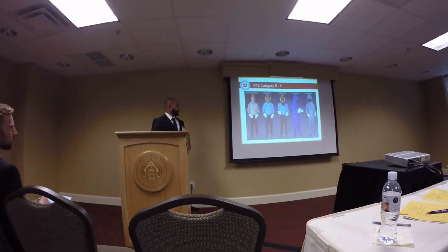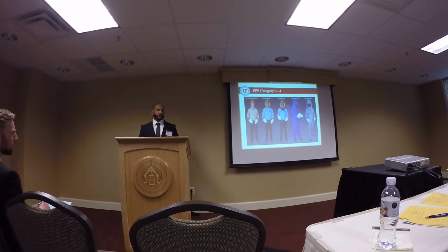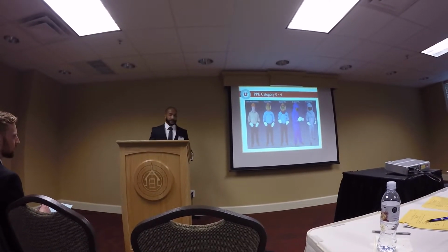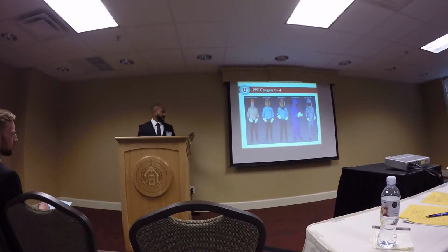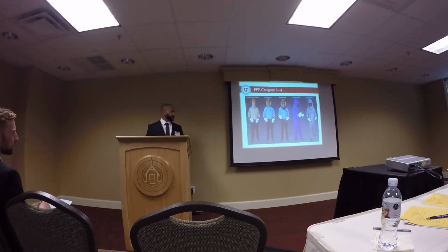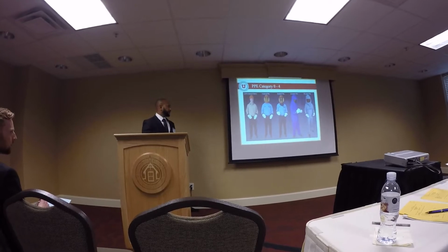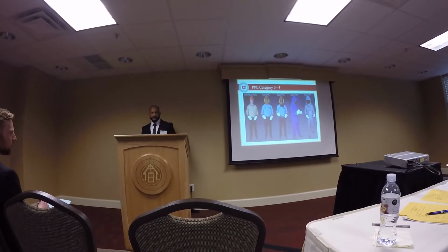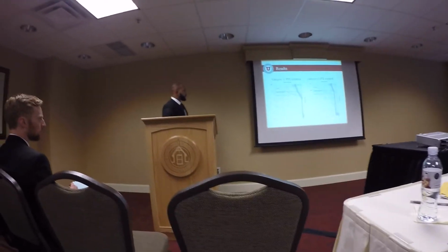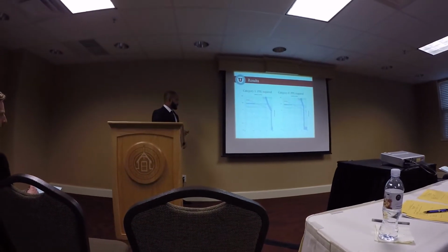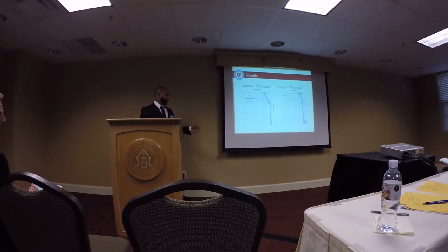Category 4 is 40 calories per centimeter squared, which is pretty much a moon suit to work on live line, which is extremely uncomfortable. I got the chance to wear one out in the field on my internship, and it's not fun. It's hard, and the mobility is extremely limited. The reason I brought this up is these are my results. A couple of the generator main breakers are sitting at Cat 3, where you pretty much have to wear a moon suit to perform any kind of operations on it.